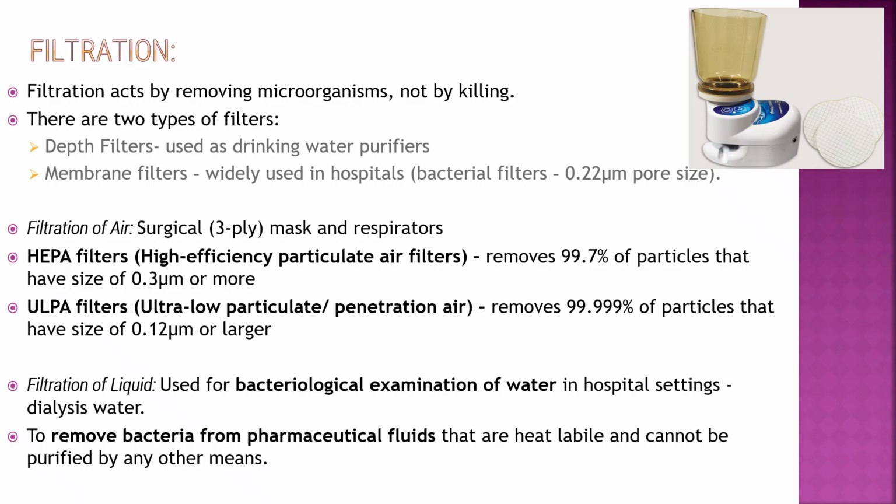HEPA filters, high efficiency particulate air filters, remove 99.97% of particles that have a size of 0.3 micrometer or more. ULPA filters, ultra low particulate penetration air filters, remove 99.999% of particles that have a size of 0.12 micrometer or larger. Filtration of liquid is used for bacteriological examination of water, in hospital settings, dialysis water, and to remove bacteria from pharmaceutical fluids that are heat labile and cannot be purified by any other means.